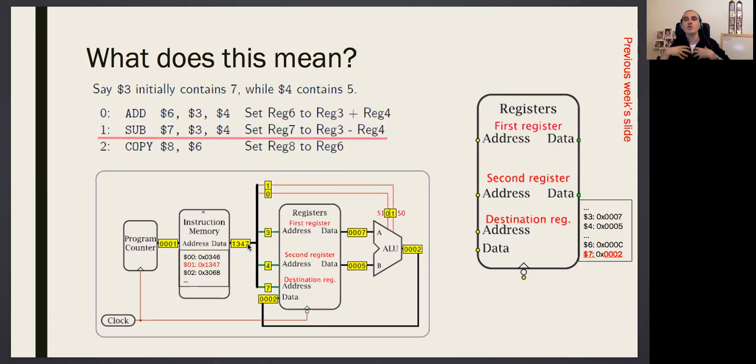As human beings, we are going to learn the assembly language. Keil, our interface, will transform it for us to the machine code, and the machine code will be run by the microprocessor. Okay? If you get into the details of the architecture, you can definitely understand what this assembly means as a machine code. For this simple architecture, we know. When I say add 6, 3, since add is 0, 0 for this ALU, I know that this is 0, 3, 4, 6. But in ARM, I don't have to know this because this is not a computer architecture course. If it was, we would be interested in that, but it is not. In this course, we are at this level, not lower.